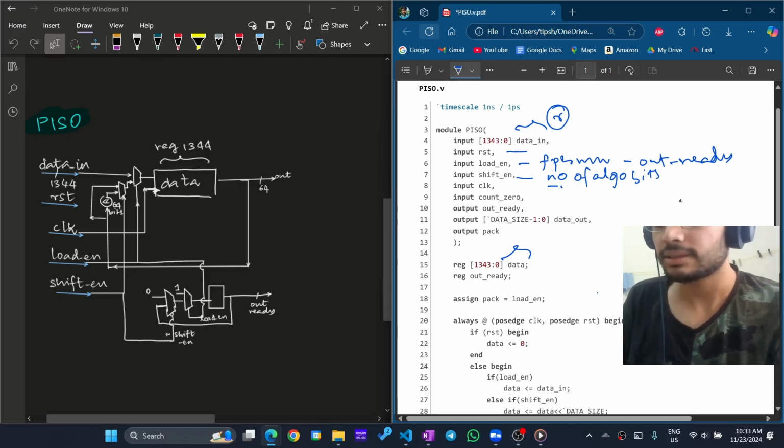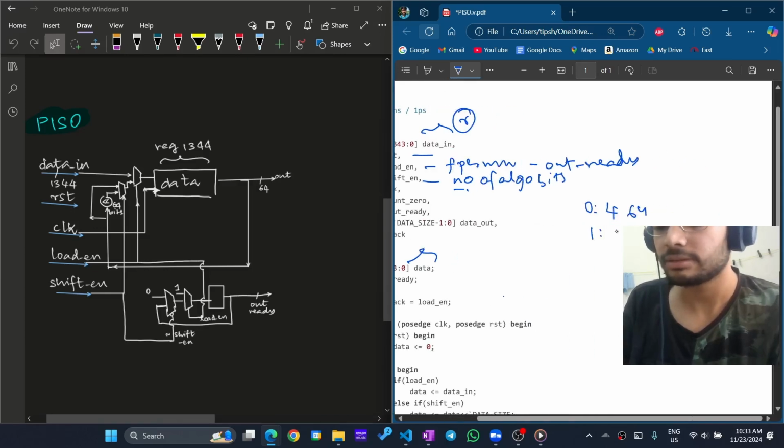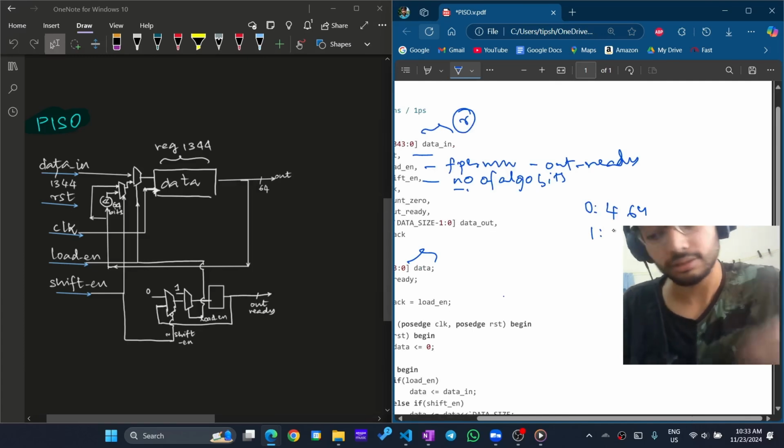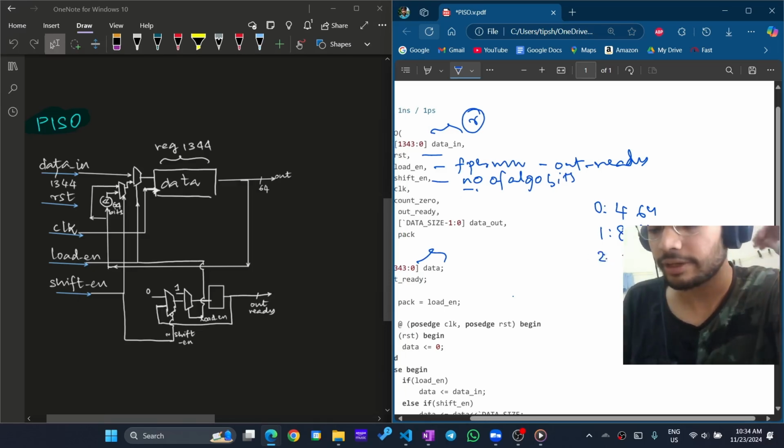For SHA3-256, which is mode 0, it would be shifting out 4 chunks of 64 bits, and mode 1 gives SHA3-512, which shifts out 8 chunks of 64 bits, and mode 2 gives SHAKE128, which shifts out 21 cycles, and mode 3 shifts out 17 blocks of 64 bits.